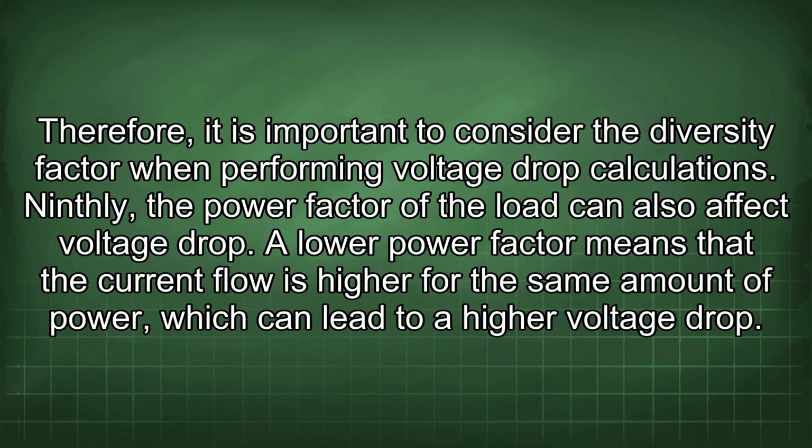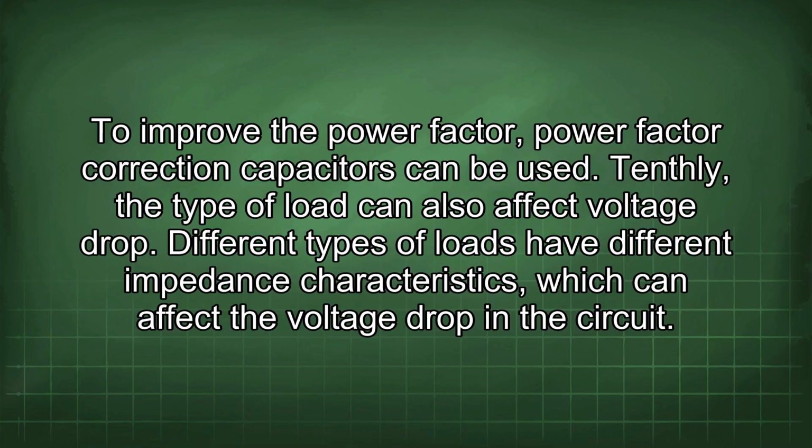Ninthly, the power factor of the load can also affect voltage drop. A lower power factor means that the current flow is higher for the same amount of power, which can lead to a higher voltage drop. To improve the power factor, correction capacitors can be used.